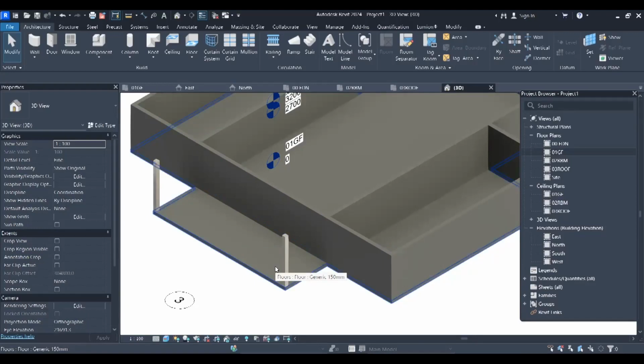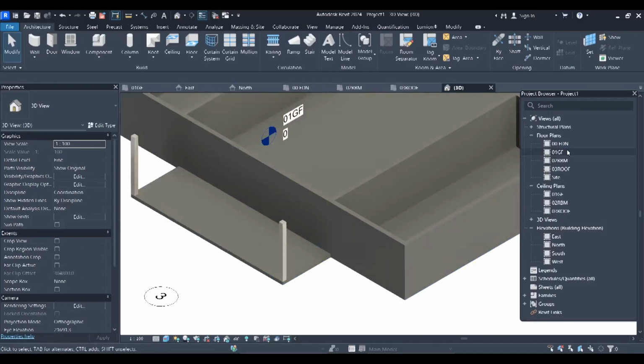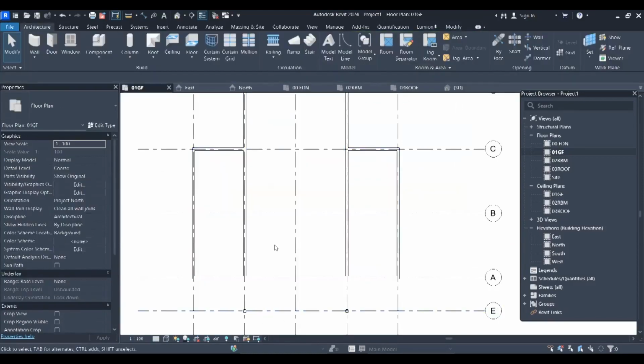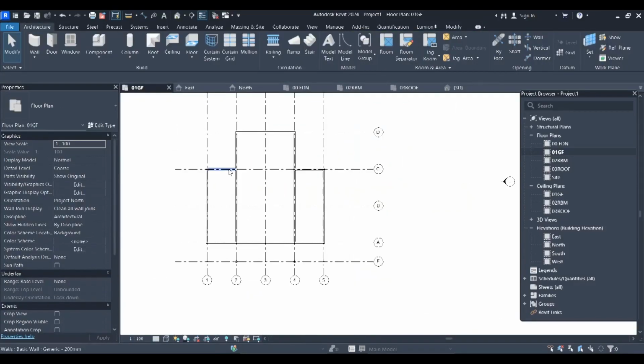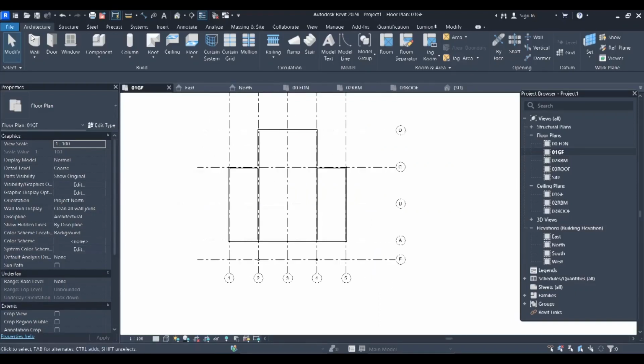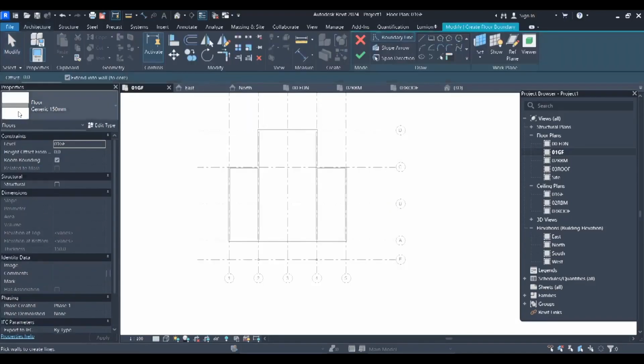Let me go back to that concept of flow. Now, let me delete this. I'm saying, if you want to place a slab on your drawing, you go to Architecture and then you will see the Floor along this ribbon, which has its tools. You expand that floor, you choose Architectural Floor, and because I had selected floor generic,